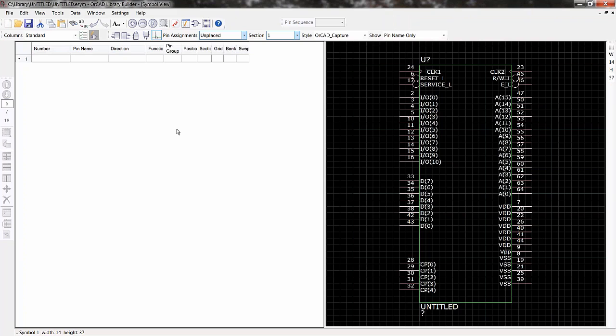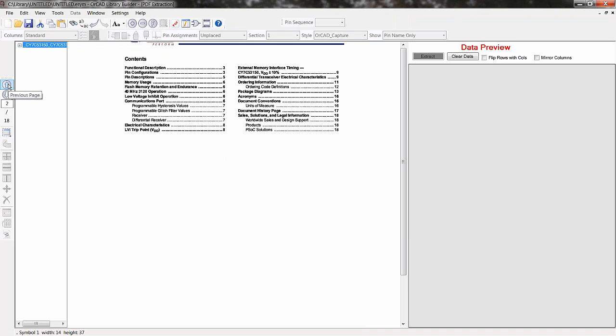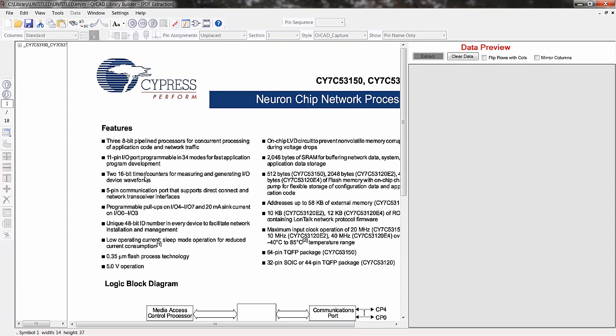And let me just give you an example of that. And then we'll get into a different style of the symbol so you can see some additional functions and validations. Let's say I needed to build the footprint. Well, what footprint do I need to build for this particular package? Typically, the data sheets are defined where you have your pin table or your graphical information towards the top of the data sheet. I told you I would do another sample here of selection.